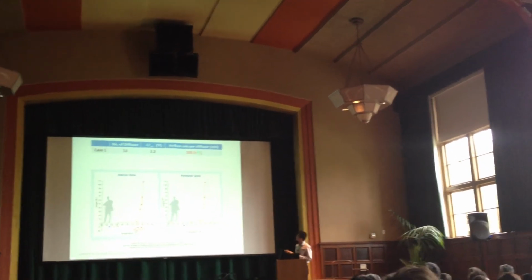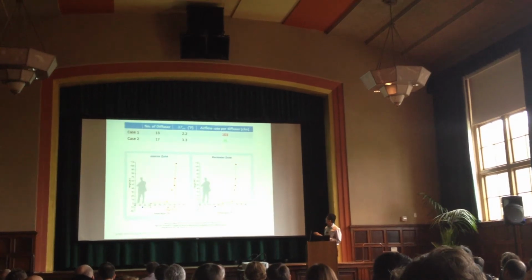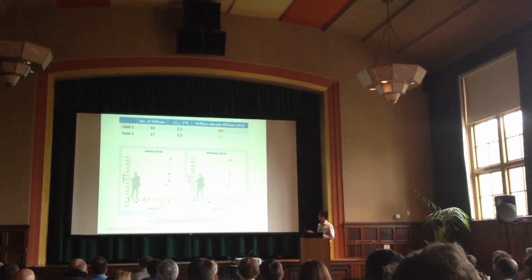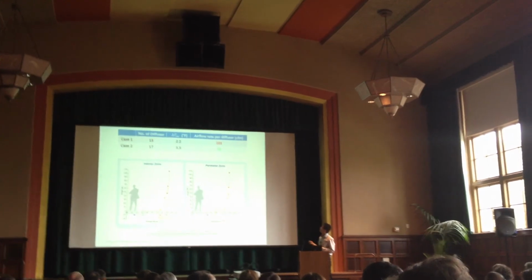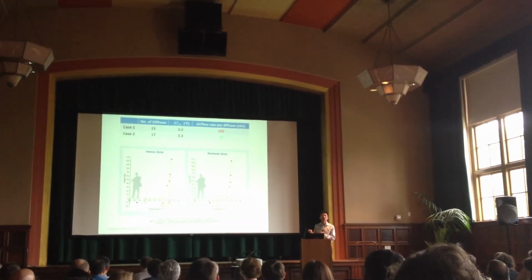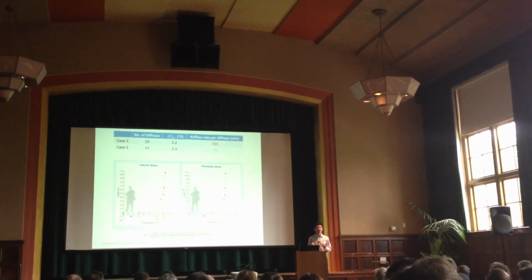In order to solve this, we add a little bit more diffusers. We add 4 more diffusers. And then we had a little bit more, one Fahrenheit degree more stratification. And also we reduce the airflow rate per diffuser to the nominal value. But as a designer, you want to have more flexibility.